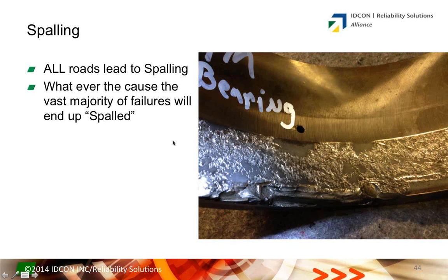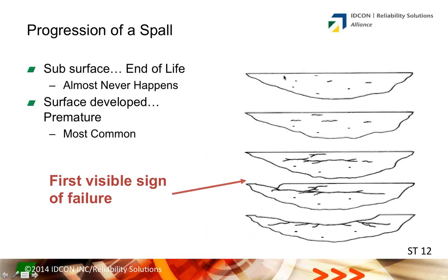Here's how a bearing spall occurs. Now this is effectively what we're looking at here. This is the surface of the bearing, and you have these microscopic, minuscule little subsurface flaws. As balls and rollers roll over this, it flexes the metal slightly, and that leads to subsurface fatigue cracking. The normal end of life for a bearing, this is what happens. These little tiny subsurface defects form fractures, and the fractures get bigger, and eventually that fracture gets to the surface. That process for a properly installed, well-lubricated bearing should be 20, 25 years or more.